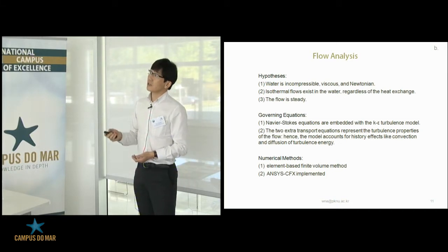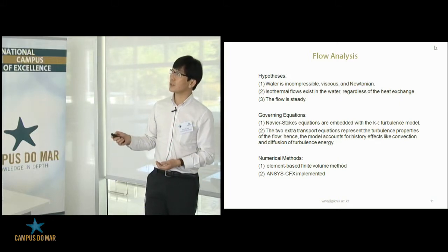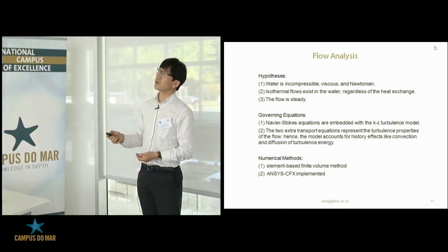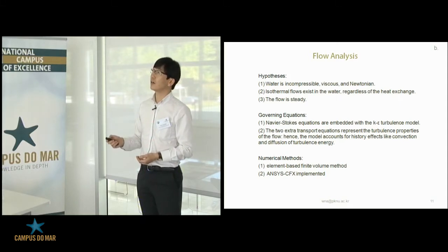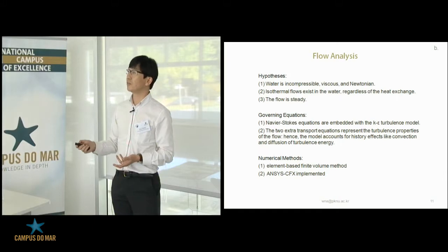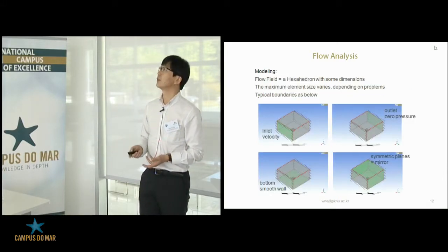For the analysis, I made some hypotheses here. The water is incompressible, viscous, and Newtonian flow. And isothermal flows exist in the water, and then the flow is steady. And the governing equation, of course, is the Navier-Stokes equation, etc. And then the numerical scheme, the element-based finite volume method, we used.